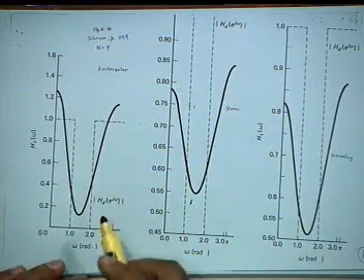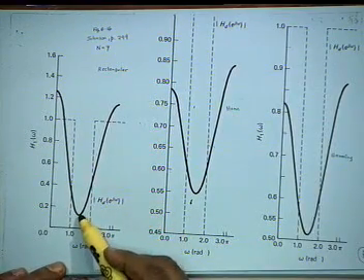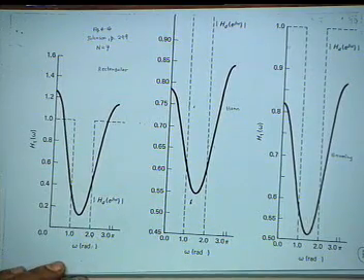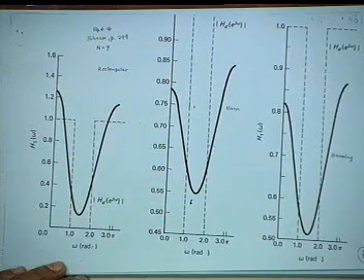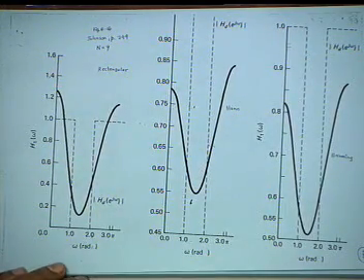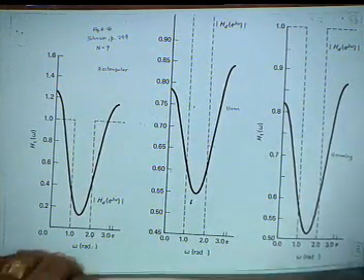After that you should compare how close the dip goes to 0. That will determine the tolerance, the stop band tolerance, and then the stop band width. So, a comparison requires further work. Just plotting this individually is not enough.